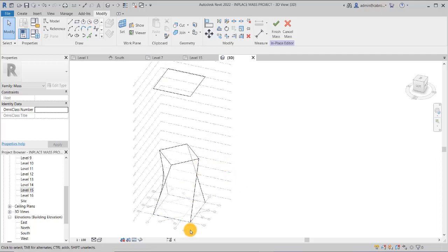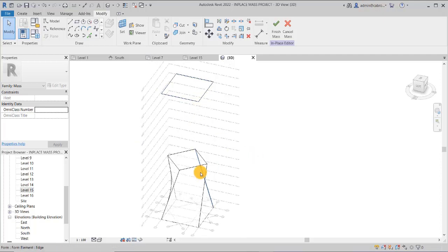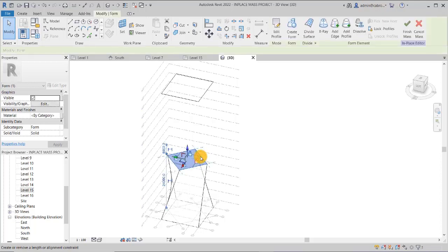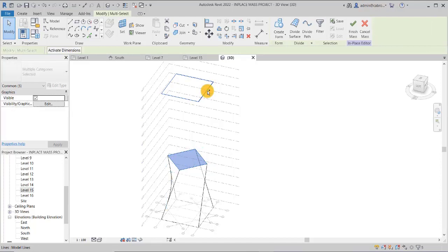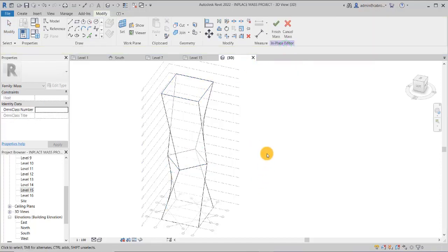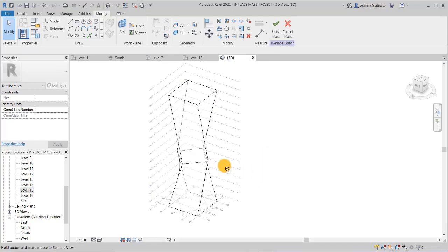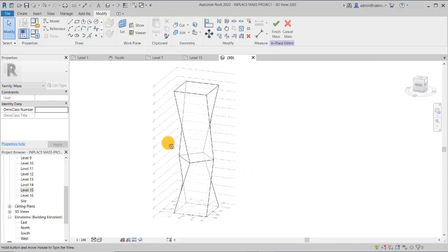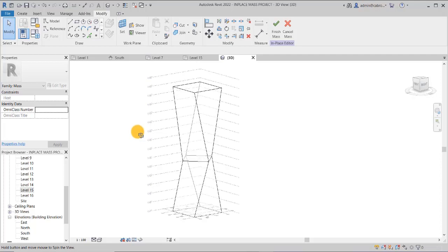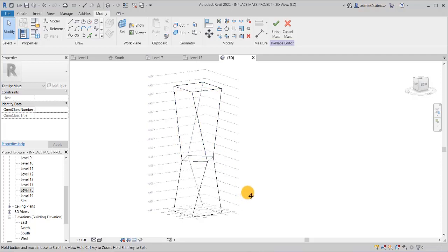If not, and I had selected the 3, it would have wrapped around with curves and then gone to the top. But this is the case. I come back again to select the top plane. So I select here, press Control, select this other plane, and then I come back to say solid form. So you see, now I have these edges, and this is exactly what our image that we saw at the introduction looks like. It's beautiful.